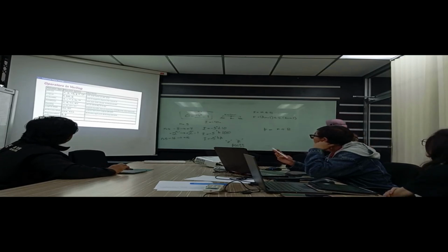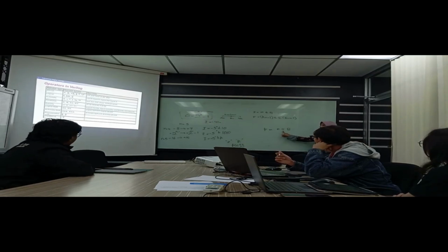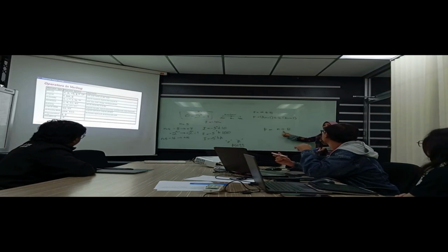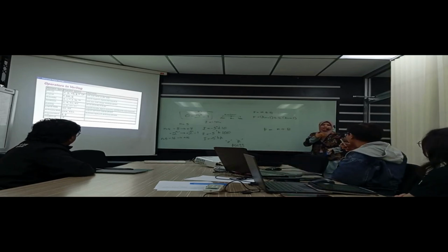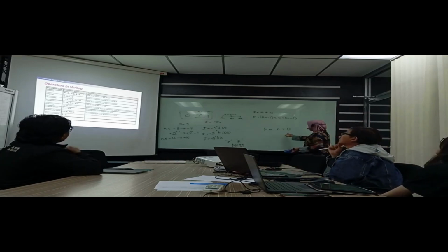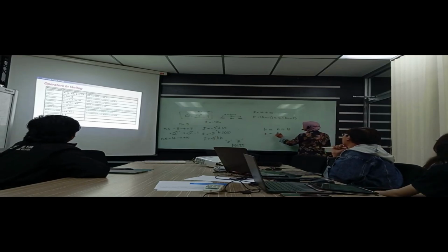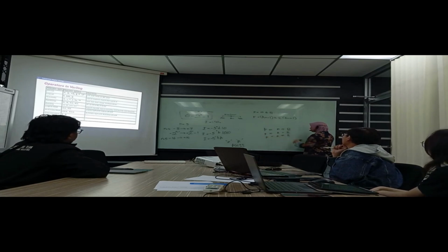So if you use a schematic, you don't have the plus. What you have is the bitwise. This must be translated to basic logic gates. But if you use Verilog, it is much easier. You can do the plus, the minus, the multiply. Imagine how to design the multiplier using the gates. Very hard. But now just use one line of code, multiplier.